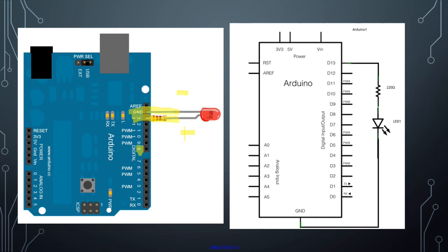The only thing I don't like about this format here is that it does not show how the breadboard comes into play. So if you imagine you would have a breadboard with a little hole here that you would plug your wire in to, maybe another on the same path that you plug your LED in. One here to plug in your resistor and another here to plug in your LED. So it doesn't show that, and we'll talk about the breadboards more in depth shortly, but just bear in mind that a breadboard does come into play with these.